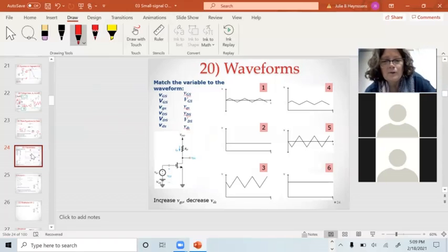We've got a voltage right here. It's a small signal. This is around 0 volts, so it's completely AC. It's small, so it's our input. So this is little v, little g, little s. If I find the equivalent of this with a larger voltage swing on the output, that is also purely AC. So this is little v, little d, little s.